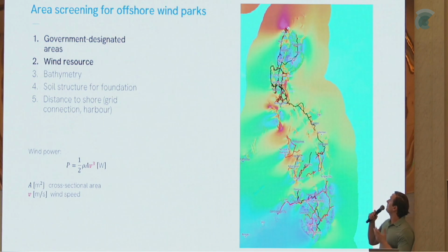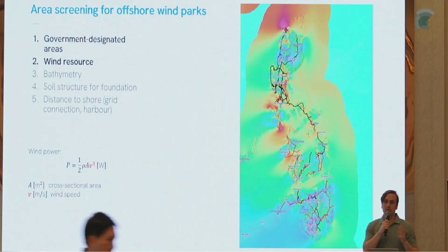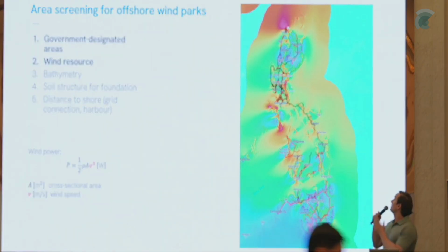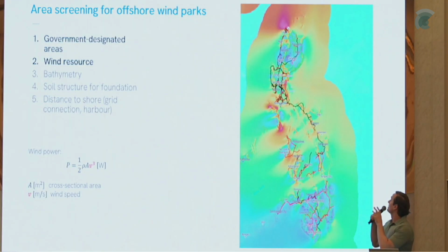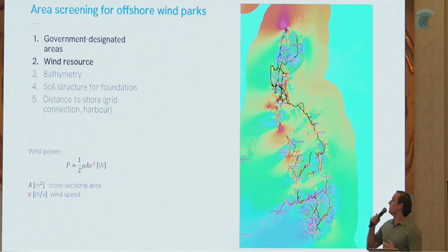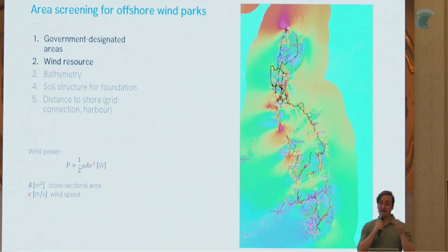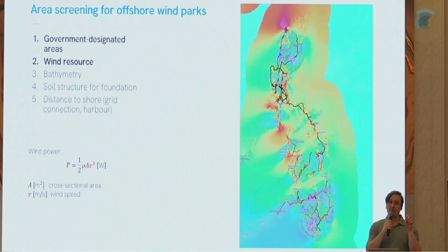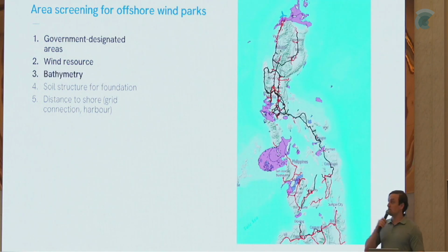Then you look at what the wind resource is. To start out with, as we always recommend, use the Vortex data to do the analysis, to look at what the wind data is at my site and what the distribution of this wind data is. I don't need to go into the power law of wind power, but I need to go through this also with the non-experts. Essentially, as wind speed is in the power of 3, even the slightest difference from your average wind speed has a massive impact on your power output and hence your business case.